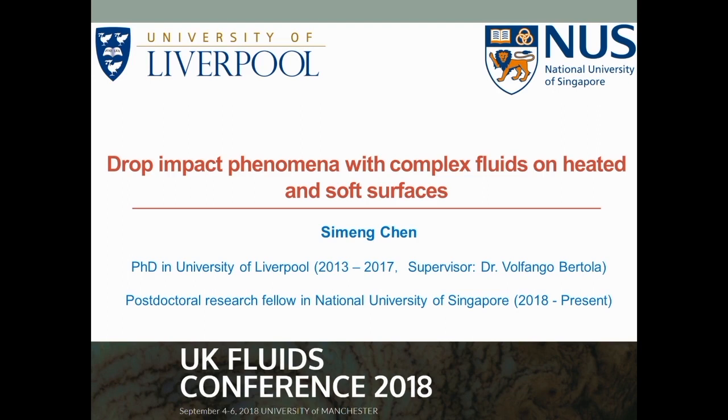For example, I changed the properties of the fluid. I used non-Newtonian fluids. I mixed water and polymers to get polymer solutions. And also I tried different types of substrates. For example, I tried a heated surface with a temperature above the Leidenfrost point. And also I tried soft surfaces which undergo permanent or temporary deformations during drop impact.